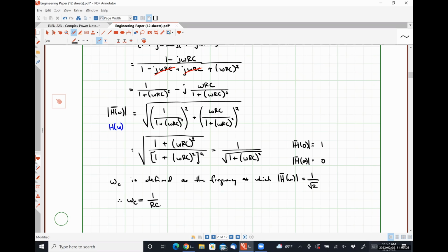When we have our second order circuits, that center frequency omega naught is literally the same thing as our omega naught for our RLC circuits. It's the frequency at which the impedance becomes purely real. But anyway, we know that we have a low pass filter. We know what the corner frequency is.